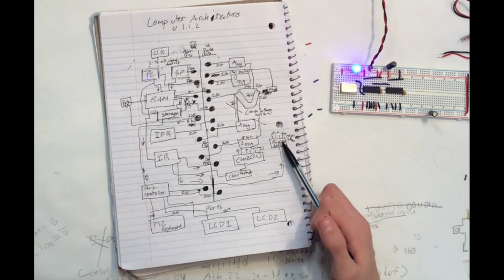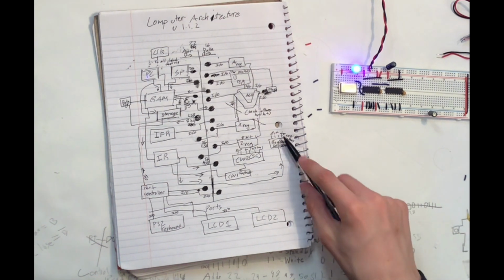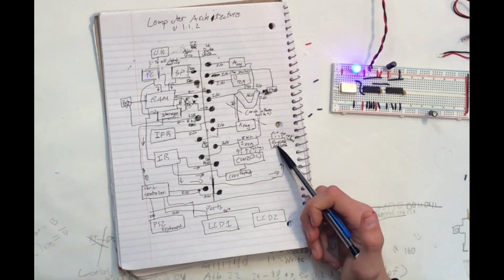And then the register decipherer, it will take in 2 8-bit codes and get the register output for it. So that way I do not have to mess around with the control word and using up like 10 to 15 control word bits, and also having a lot of different instructions just to move registers. Instead, it can just be a different code for that. So that will be very handy for that.